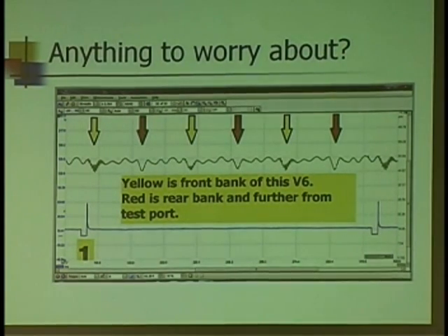If they were dirty, if there was a problem with sticking or restricted flow or something along those lines, would I expect that squiggle to be accompanied by a change in the amplitude, how far the pressure dropped at the same time? That might change my direction, my thinking. And the more you know about how the picture is supposed to be, how the system works, and apply that to the information you have on your screen.